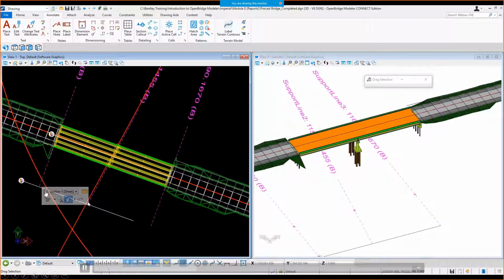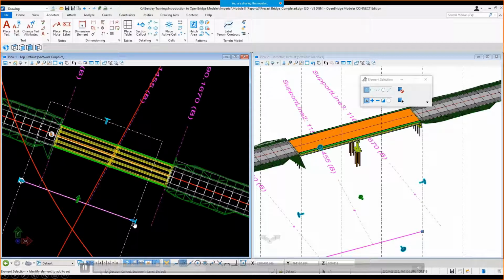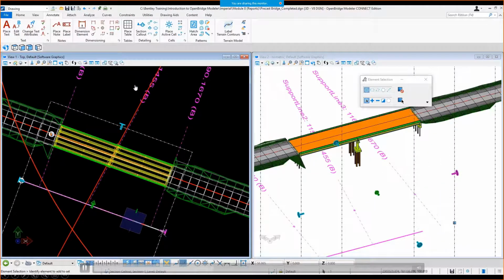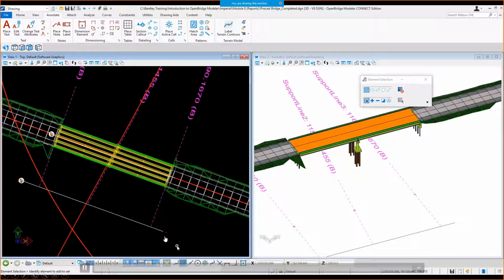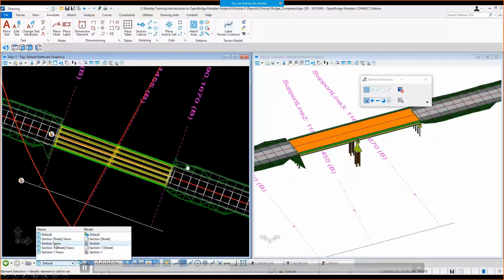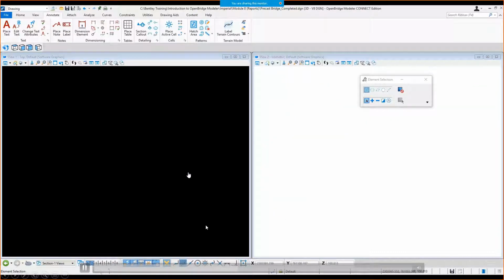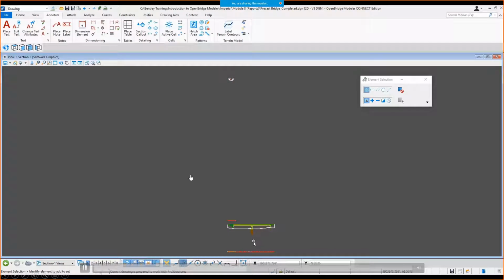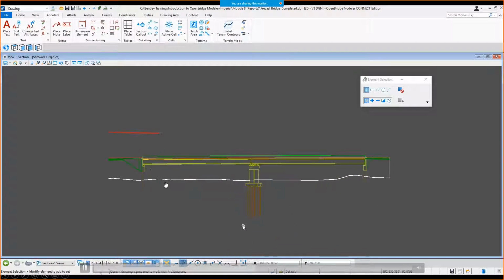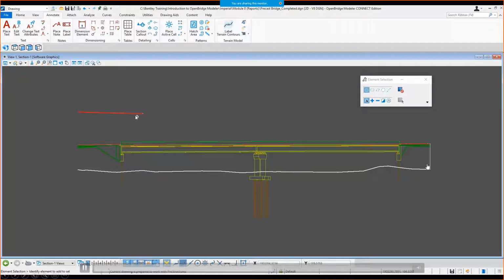And you can always adjust the lengths of these lines and the area you're seeing by grabbing these push pins and stretching them, and then you go back and look at the resulting model. And whereas before I was barely picking up each abutment, now we're picking up part of the roadway and maybe some wing walls and anything else that was modeled as part of that particular structure.